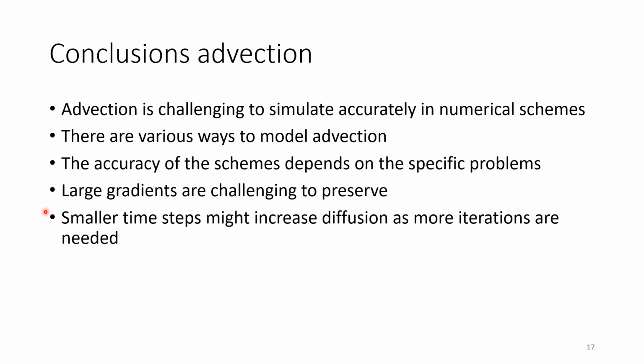Again, it very much depends on the scheme and how it is implemented in the program, but those are phenomena that might occur, right? And if you have a new model or are using a new kind of program, to get to know the program, try to simulate just a pure advective problem. Try to set the diffusion to 0 and just see what the program is doing and how well it's handling diffusive problems, advective problems. Pardon.